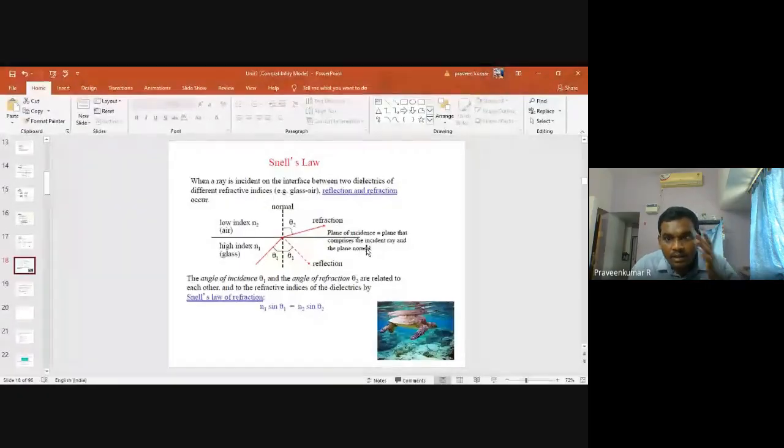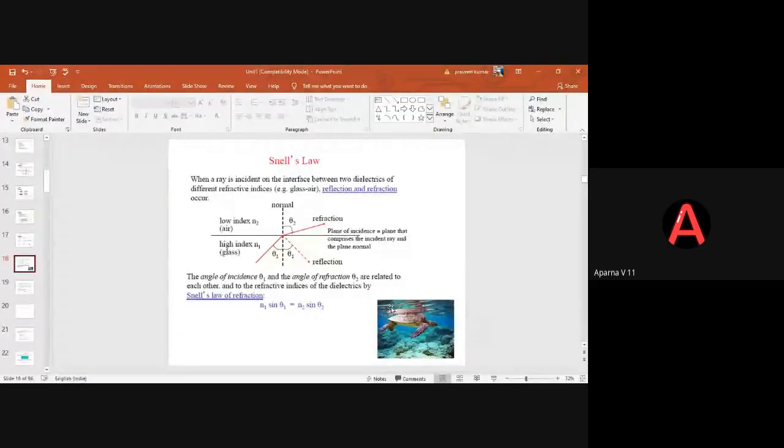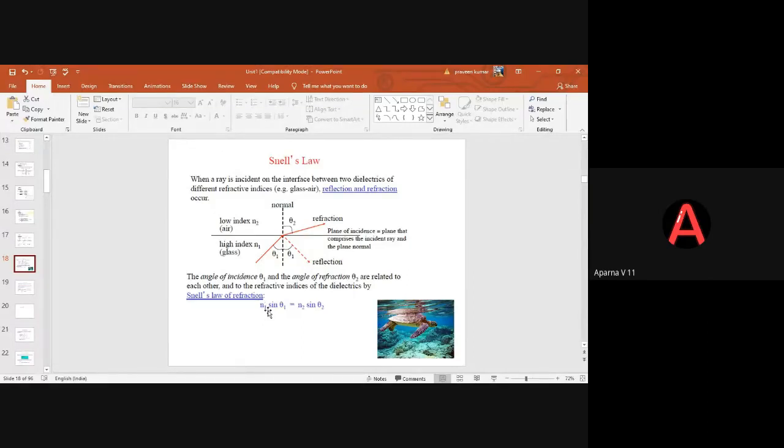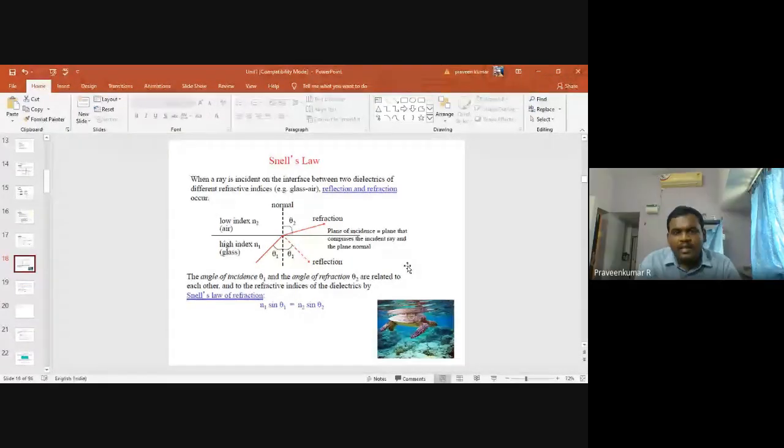Can you see here? So this is the idea. Aparna: So when the incident angle is greater than the critical angle, it leads to reflection, right, sir? So the information will be passed only in the core. It won't lead to any loss. But you said previously that when the incident angle becomes greater than the critical angle, it leads to loss, and the information would be transmitted to the cladding. No, that is the thing. You have to understand what N1 and N2 you are considering.